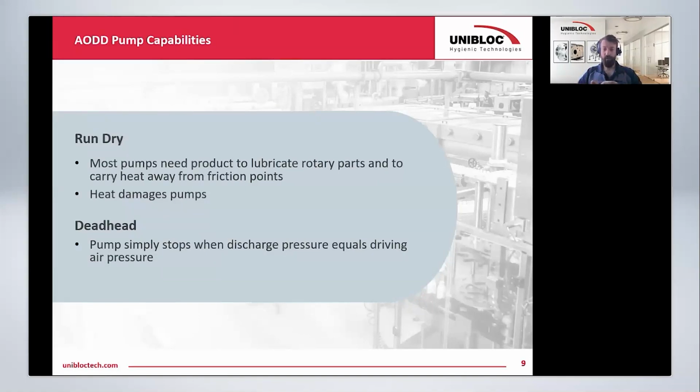So where deadheading on most pumps is an accident and can quickly lead to failure, on an AODD, deadheading can be used as a method of operation. I've had several customers who transfer product from a mixer to a hopper on a filler or something like that. They just have a valve at the hopper, and when it's full, they'll close it, and then the pump will stop pumping. When they need a little more in the hopper, they just open the valve, and the line pressure drops, whereas the air pressure is the same. Since the air pressure is higher, the pump just kicks back on and starts pumping again. So if there's ever a chance for deadheading, an AODD is a great option.